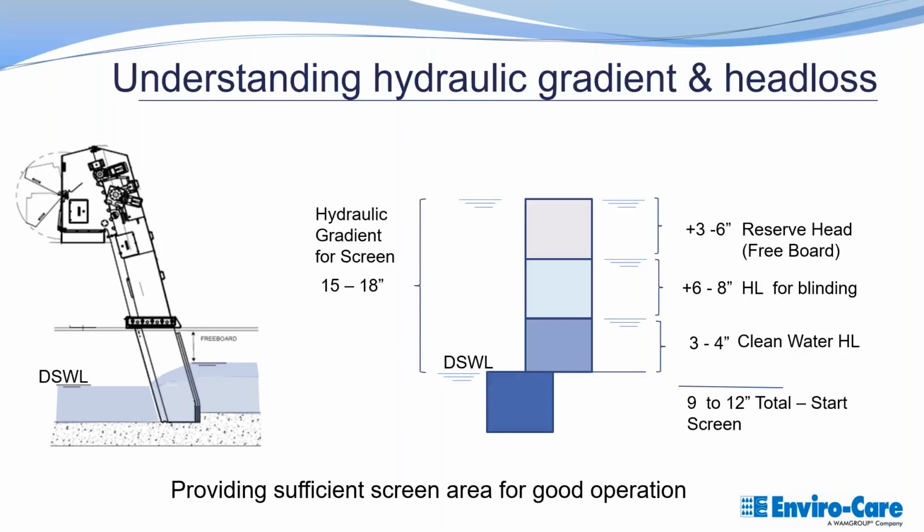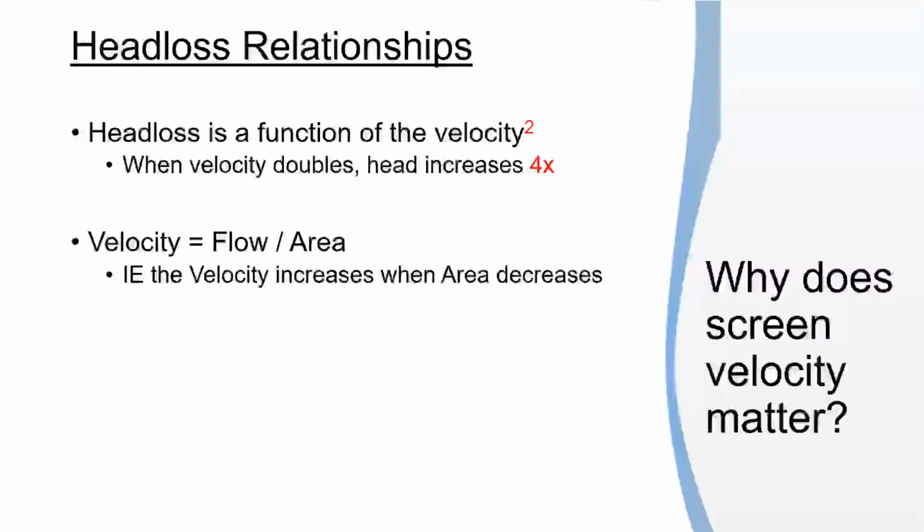And then of course, one of the other variables is nobody knows exactly what's coming down the flow when. So asking how frequently the screen runs will really be kind of an immediate question back. What's your loading rate for the debris in the screen? So it's all important considerations, and it does complicate the head loss discussion quite a bit.